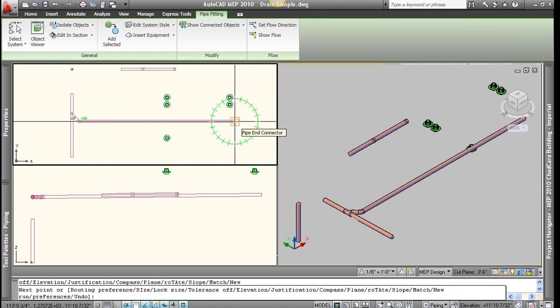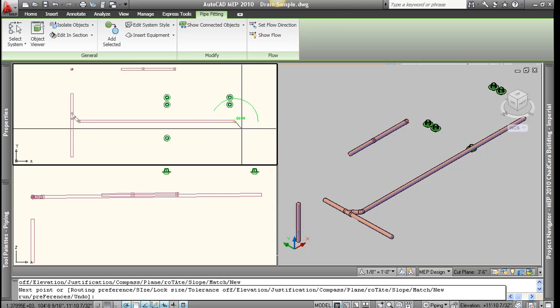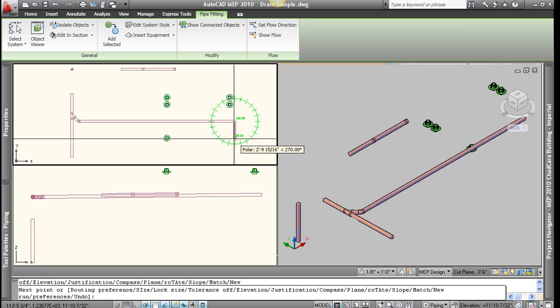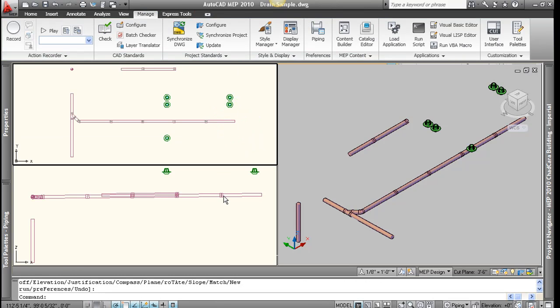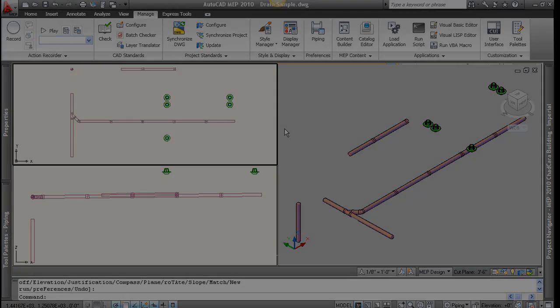And notice that when I do, as soon as I select that, I get the pipe to appear in all the views, an isometric and an elevation. And in elevation I can check right away that indeed it's pitched, so I got what I was expecting. And I can finish the command and my stick lengths come in and I'm getting exactly the kind of behavior I was expecting. So what have we covered real quick?